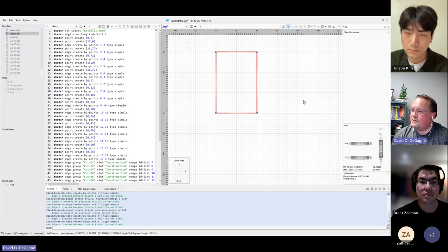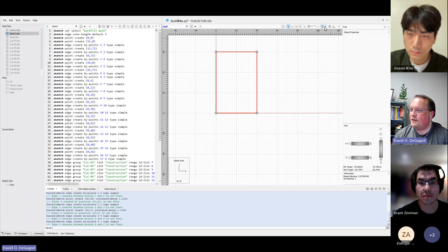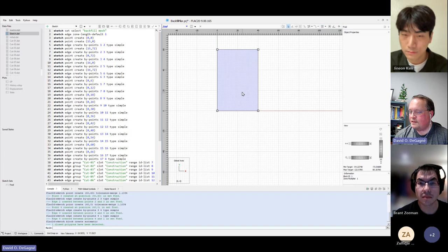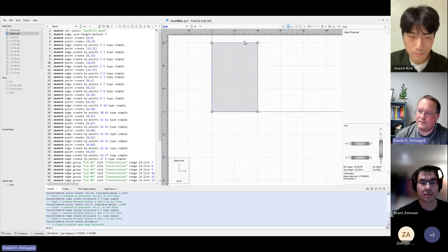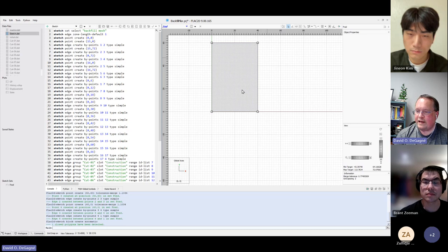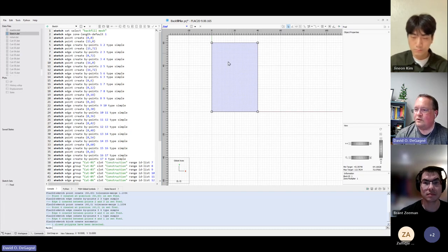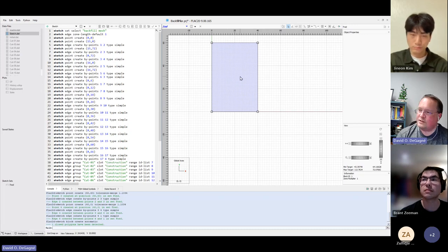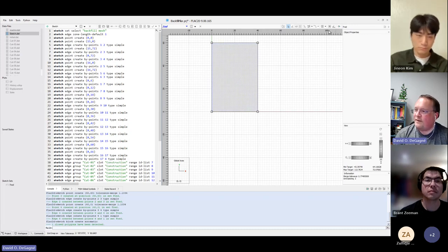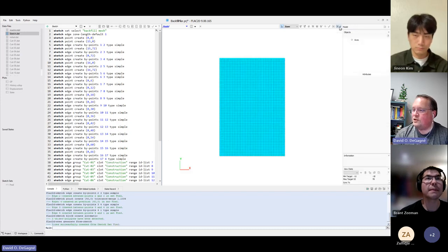And then if we just want to keep it as simple as that, that was our model. We can go in here and then we can mesh all polygons, and we get a simple mesh. It's a very simple model, so everything's just little quads. If we had a slope, essentially it works and tries to generate a hex dominant model. So you'll have mostly quad zones, but you may have some 3-sided zones as well. That's all perfectly valid.